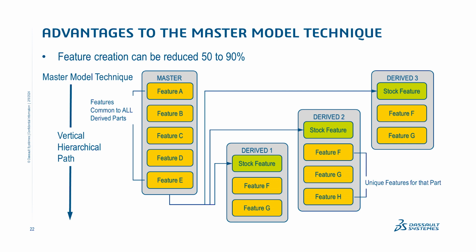It is a hierarchical process. That's why it's called master-slave. Well, it's not politically correct to call it slave these days, but that's why we call it derived. So you have a master that's always driving. It's always the master to all of its derived or child parts. And that's by design intent. You want that. You want it to be a one-way path, because you never want the derived parts affecting the master, because that would affect the other derived parts.